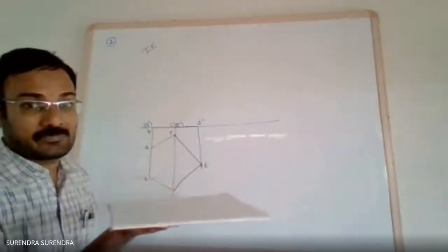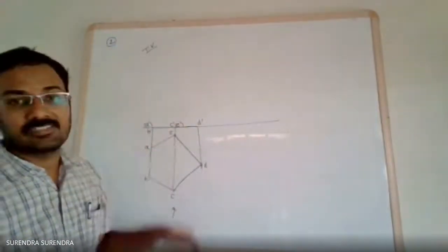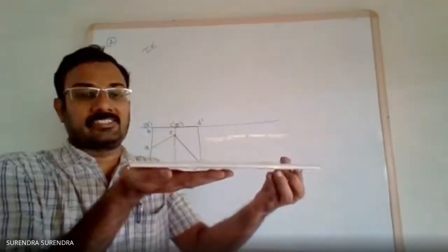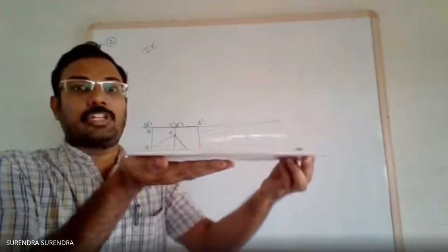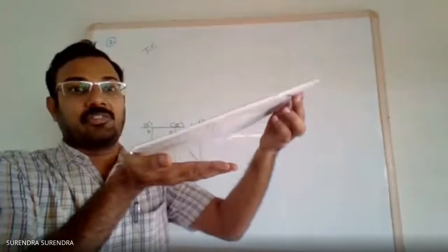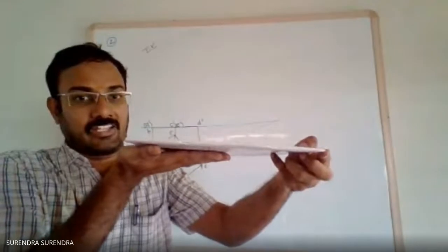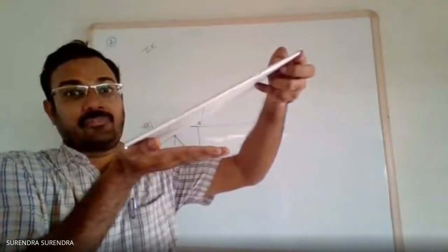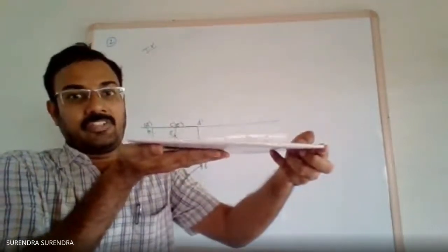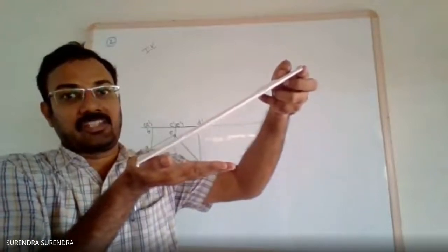And then with respect to the front view, as the assumption is resting on the horizontal plane, we have drawn this line on the XY line. Now rotate this to 45 degrees. So rotate just the same on the front view. A line is rotating. Initially it is on the XY line, and rotate this line for 45 degrees and redraw the front view. The front view we draw now is a line on the XY line. Now rotate this front view for 45 degrees and redraw.